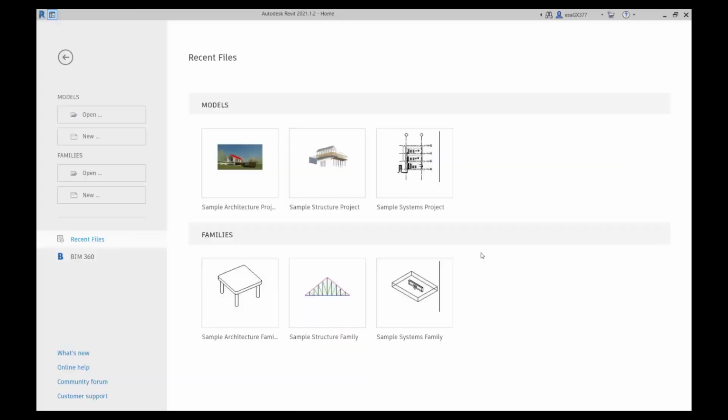Now we will see how to work on Revit. If you do the planning on Revit and U values are already inserted into architectural components, for example by the architect, you won't spend time adding these values into the components. All you have to do is detect the building with zoning and add missing parameters.